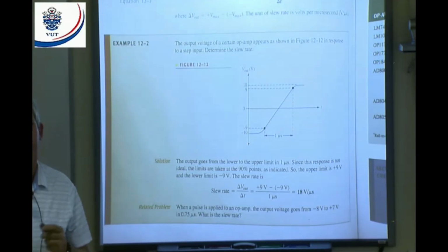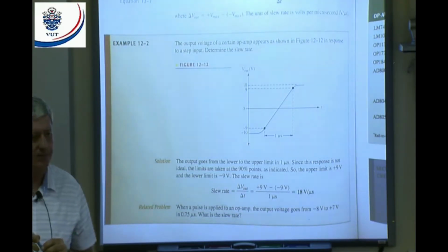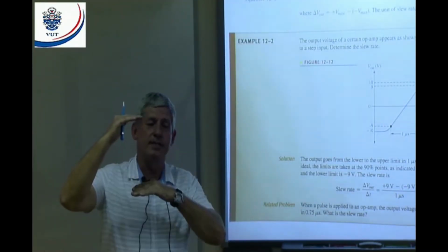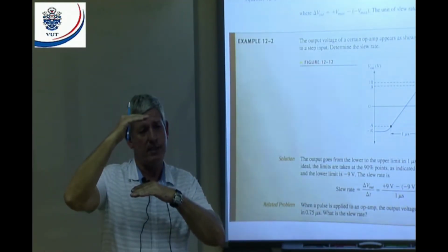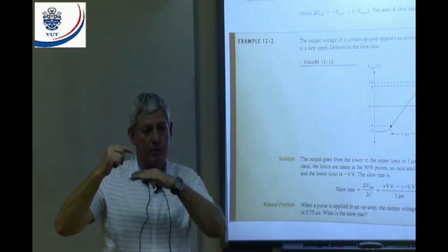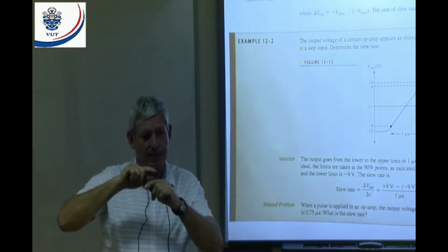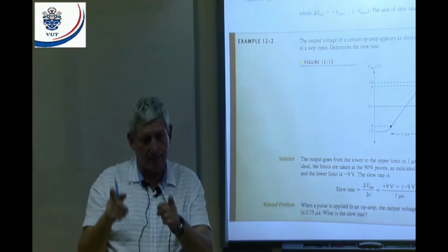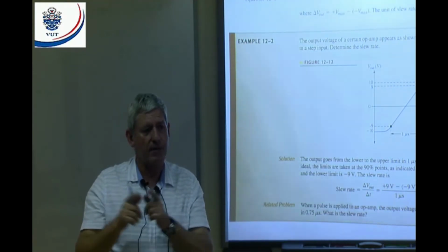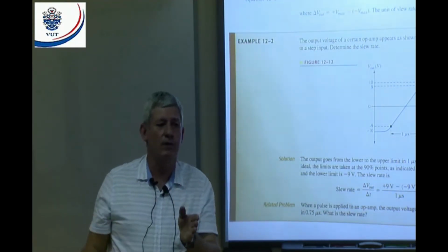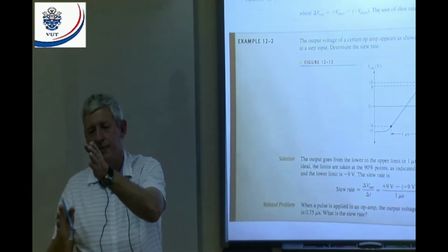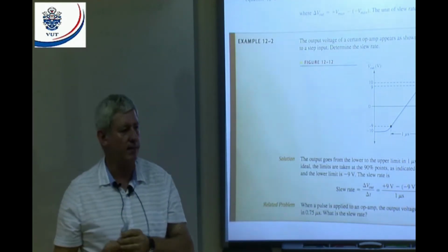Now, if you want to determine the rise time of any pulse or the fall time of any pulse, you will put it between the 0% and the 100%, all right? And then you will work to 10% and 90%, and then you will determine that time. That will be the rise time of the pulse, all right? Same with the fall time. You will go from 90% to 10% to determine the fall time.